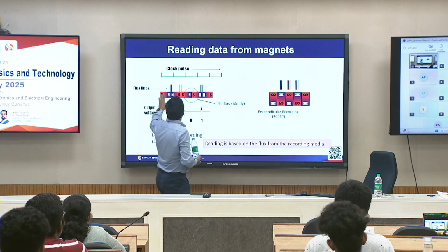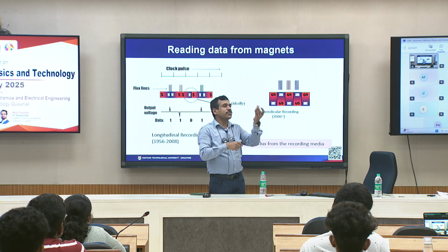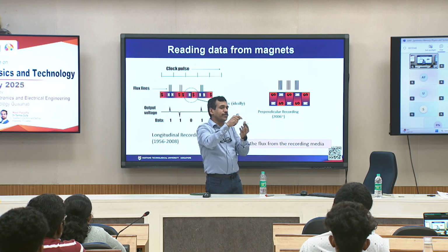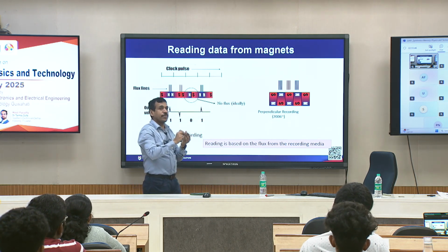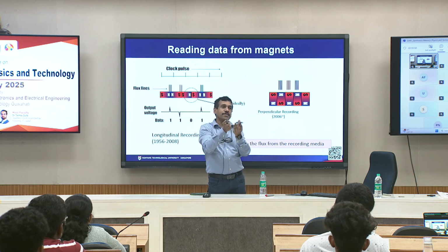Okay. So, in longitudinal magnetic recording, you have a disc, and on the disc you have a film. In the film you have grains. Those grains have easy direction in the plane of the disc. So, you magnetize them either pointing in one direction or the other.